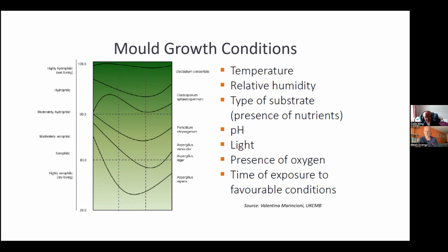Yeah, absolutely. Internal wall insulation is technically the most challenging to get right. Mainly because it puts the structure, which may have historic moisture in it, on the cold side of the wall. So you're more likely when you have internal wall insulation to run the risk of interstitial condensation, because what you've got is that cold interface of the new insulation and the old existing structure.